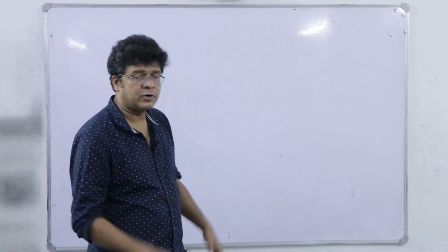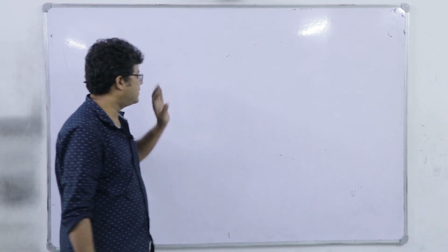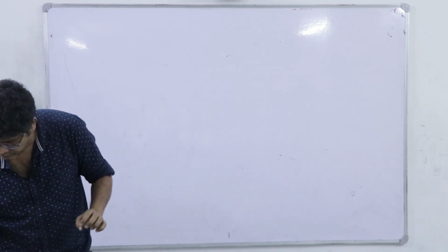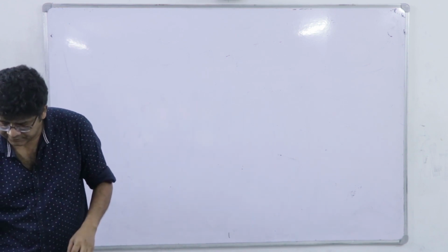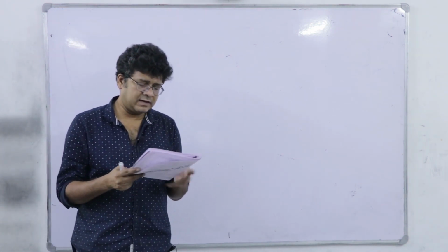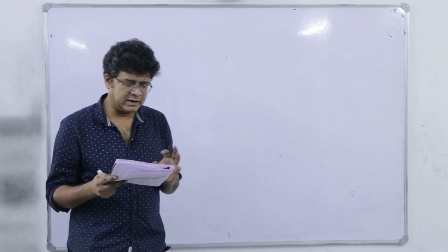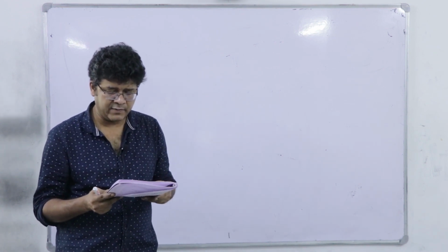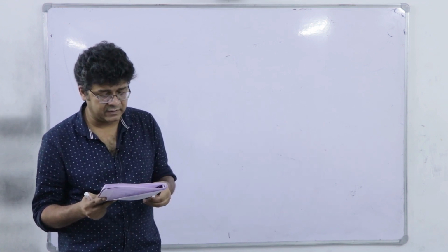So, next the point is, before we go for the working dimensionless equation, we have to know the collection of dimensionless numbers. I am not writing the first one, the Nusselt number, which we all know, hL by k, the wall temperature gradient divided by the temperature gradient across the fluid.